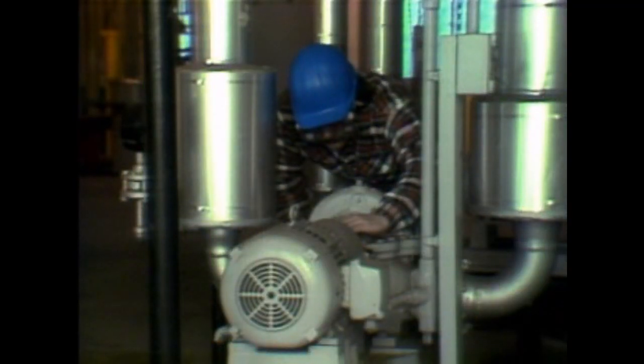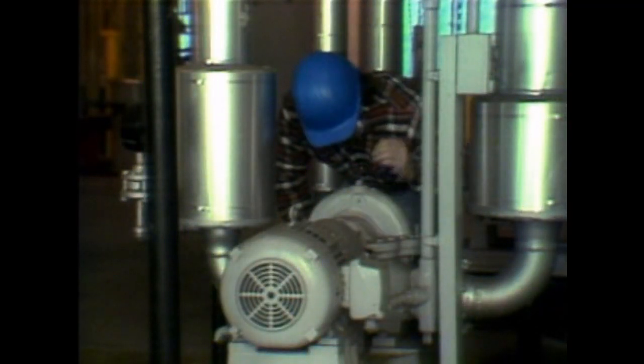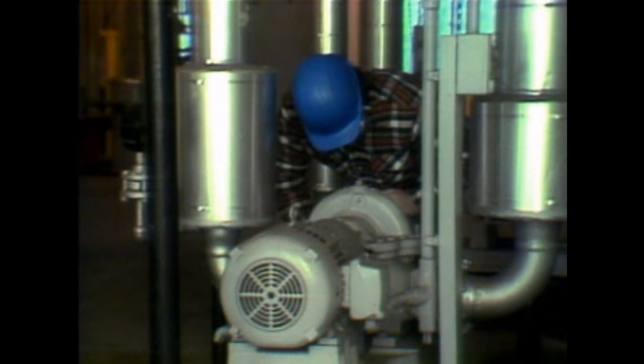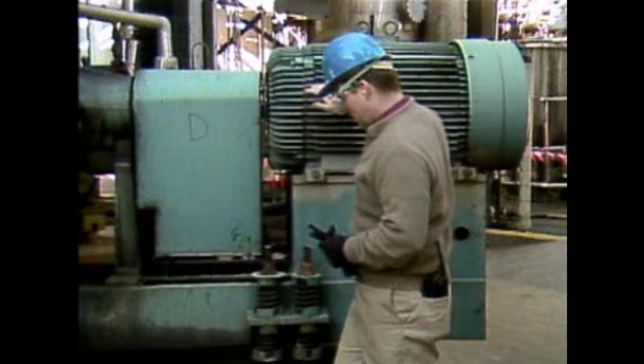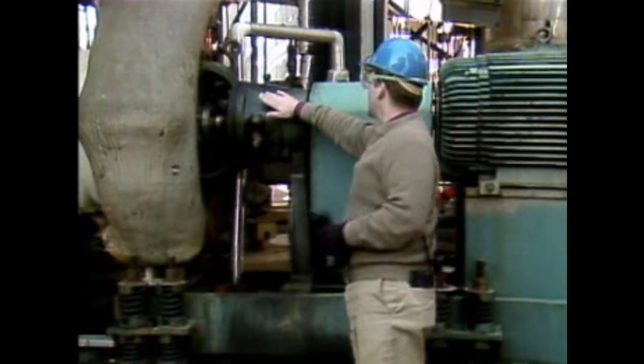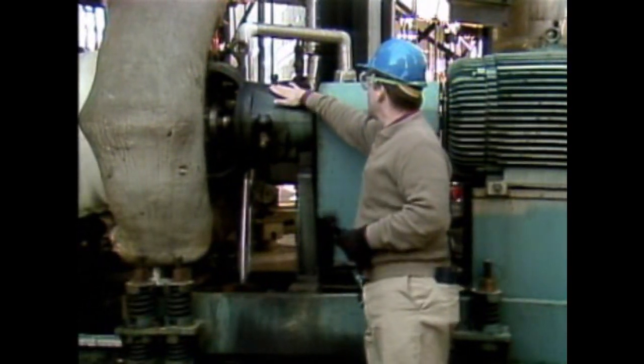In addition to looking at instrumentation, the pump itself should be checked for symptoms of problems. For example, operators should check for overheating by feeling the pump and motor casings and the bearings to get an indication of their temperatures. However, this must be done carefully because overheated components could cause burns.